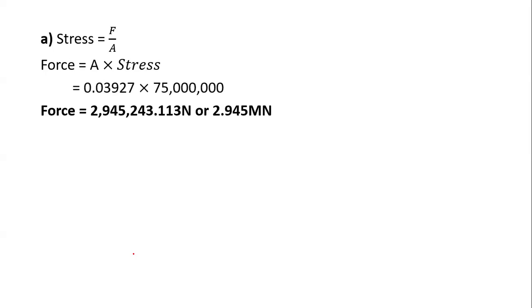So I start with the first one. I'm looking for the force. Since I already have the stress, I can make force the subject. I'll simply say force equals stress multiplied by the area. Basically, I'm just cross-multiplying. So 0.03927 times 75 million. Then that's my answer, 2.945 meganewtons.